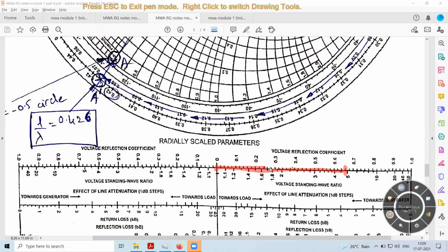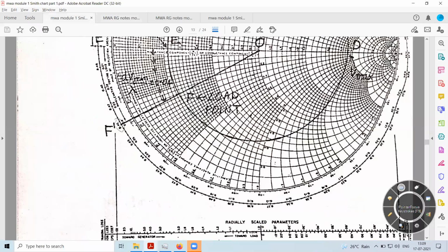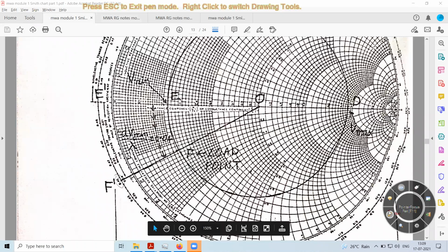Now you have to measure the length of this, from, say, point O to the VSWR point, which I'll mark as point A. So you have to take this distance. Once you mark this distance, you have to draw a VSWR circle of that radius I have specified. This distance is equal to the distance associated with rho equal to 4.48 on the VSWR circle.